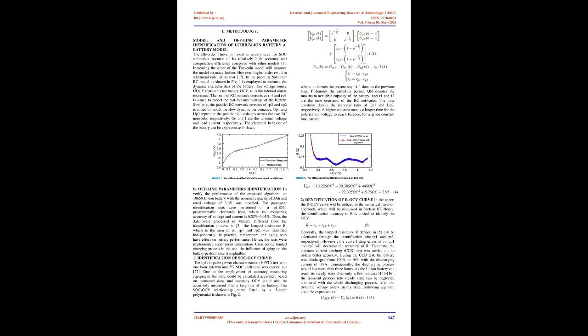In order to solve the contradiction between SOC accuracy and calculation cost, the ICC approach based on numerical iteration is proposed, where the battery model based on a second-order RC circuit is built firstly with SOC-OCV curve, R-OCV curve, and inner parameters identified offline. Then, the SOC is estimated by the CC approach in the unsteady state of the battery but by a numerical iteration approach in the steady state. Consequently, the accumulated SOC error from the CC approach can be corrected through the numerical iteration approach.